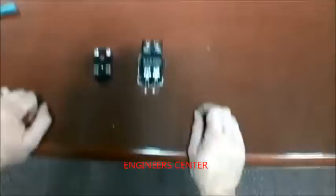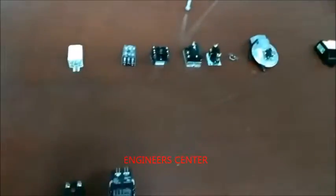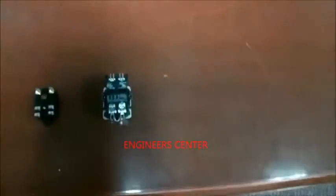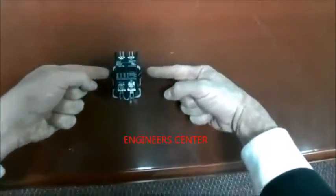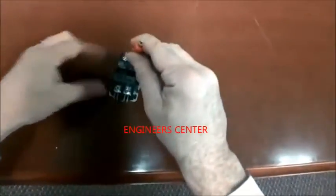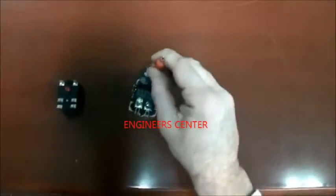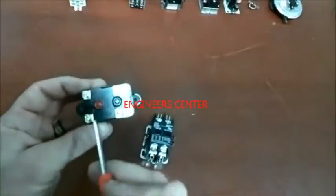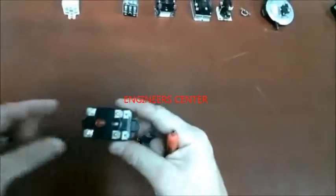What differentiates these type of relays is what tells them to open or close. So this contactor is told to close by getting a signal of 24 volts to the coil here, which will then close the contactor, sending power to your components. The relay would in fact do the exact same thing. If you read it here, you could see that the coil is 1 and 3 here and here, and so if you were to give 24 volts to this coil,